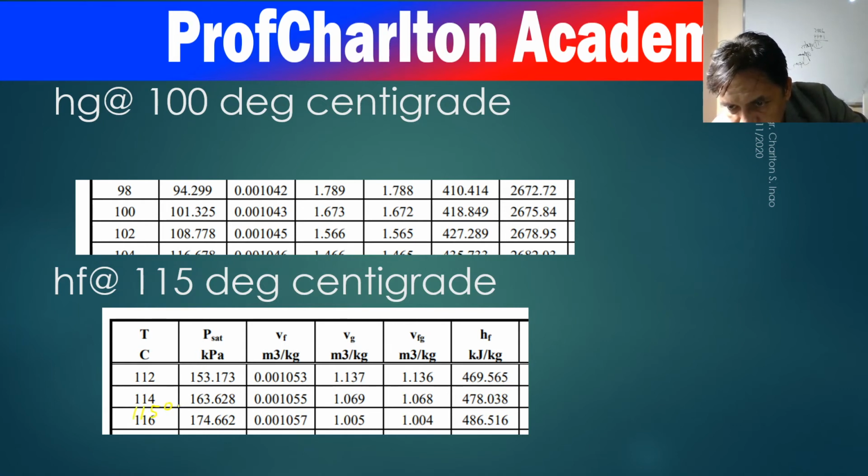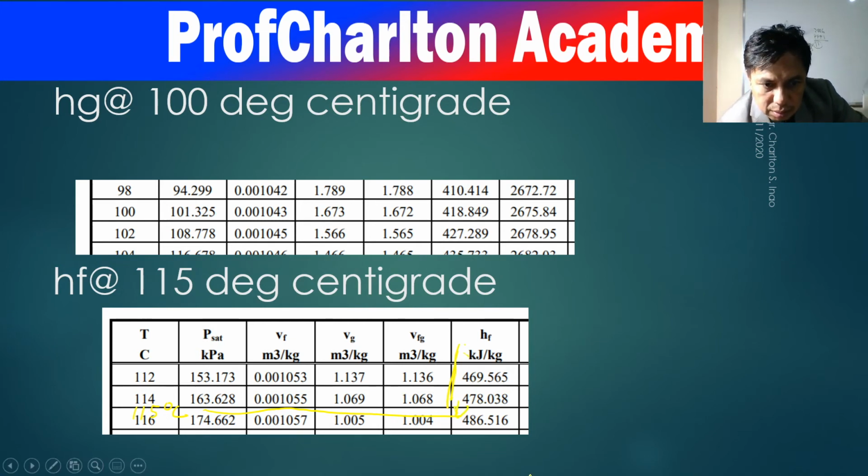So at 115 degrees centigrade, you project horizontally until you reach the HF, the enthalpy of fluid at saturation point. Let me draw the line going downward. So what you have is here.